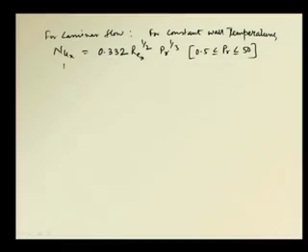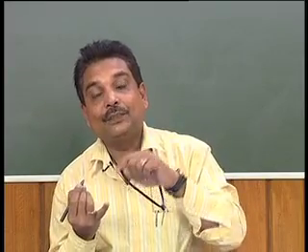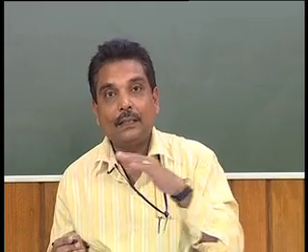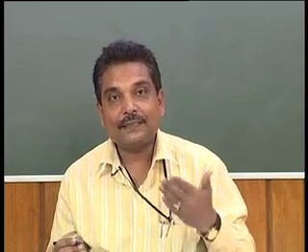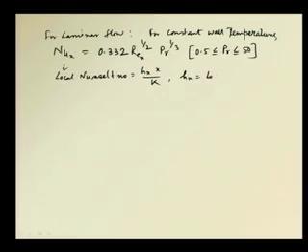Okay. And one thing we can say here is that this Nusselt number is also called the local Nusselt number, and this is equal to Hx x by k. So, we can understand Hx is the heat transfer coefficient at point x. So, the heat transfer coefficient is a function of x. As we go along the length of the plate, the convective heat transfer coefficient will vary. So, this Hx is called the local heat transfer coefficient.